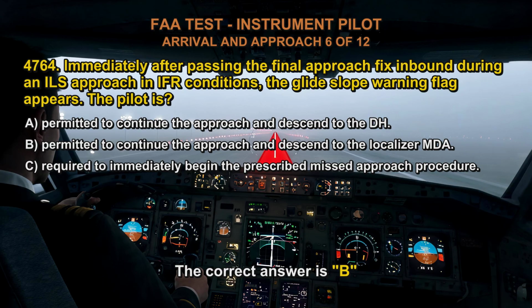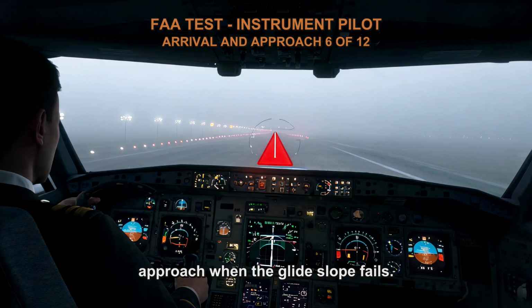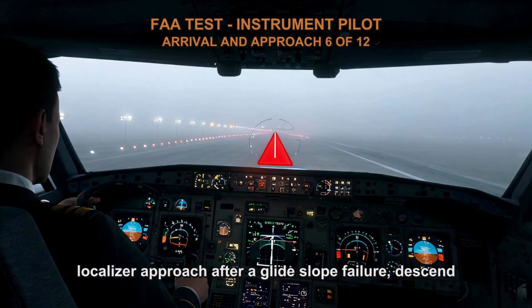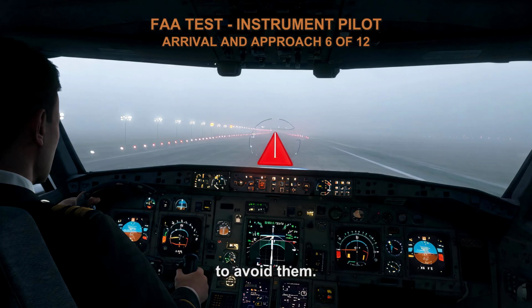The correct answer is B. The ILS falls back to a non-precision localizer approach when the glide slope fails. The pilot is allowed to switch to a localizer approach after a glide slope failure, descend to the localizer MDA, and take appropriate steps to avoid obstacles.